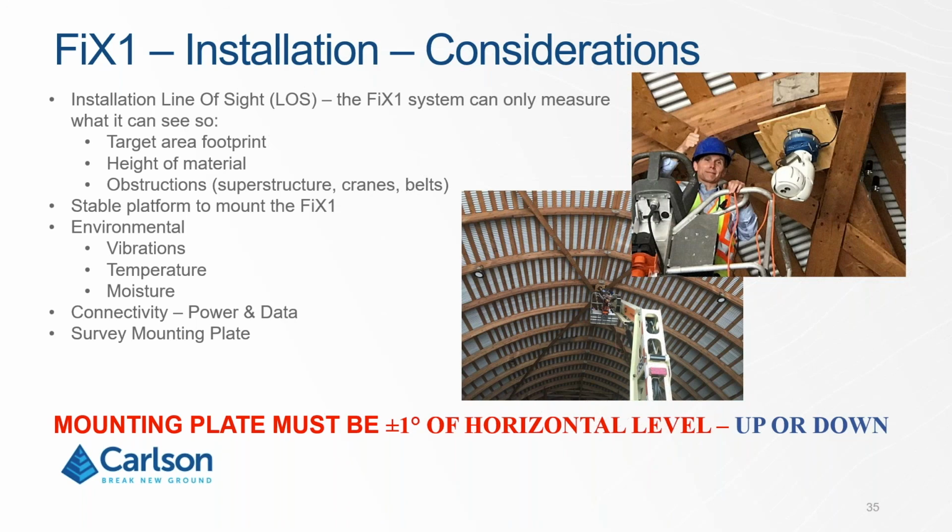You also want to consider the environmental effects when you set it up. Vibrations: you don't want to set it on top of a crusher that's going to be vibrating all the time, during collection and even when it's not collecting, because vibrations over time will wear or tear down the equipment. Temperature: you want to make sure that it's an area that's within the temperature range of minus 40°C to 50°C, but also you don't want to be putting it right next to an exhaust, where you get big temperature differentials. So that's important. And moisture. It is rated for dust and splash proof, but obviously you don't want to mount it underneath a faucet or having water leak all over it, because that could affect the laser and over time add to erosion and corrosion of the device.